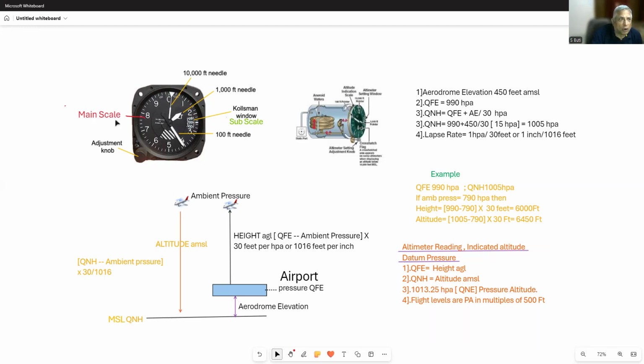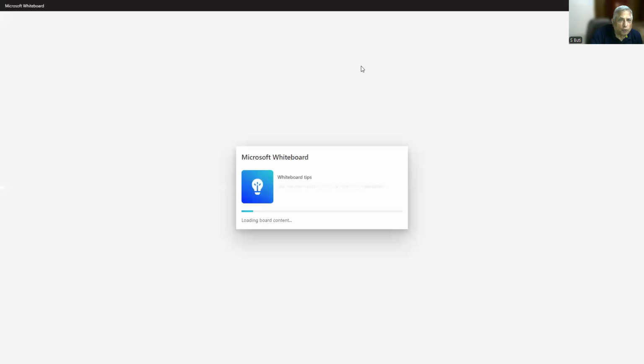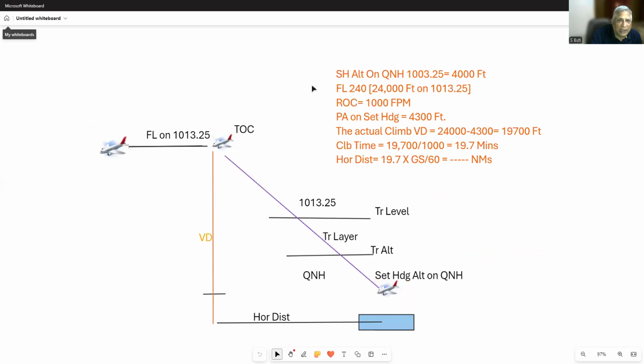Different flight levels are allotted to different aeroplanes, and when you are flying over any particular place, if an aircraft is crossing you from the reciprocal side, or from left or right, don't worry, there will always be a difference in the flight level and you are safe. Of course, don't forget to maintain proper flight levels. The slight errors in the flight levels have been catered for in giving you this 500 feet minimum spacing.